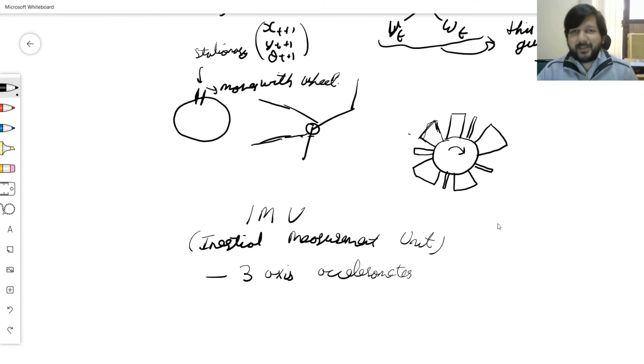Now the problem is the accelerometer is placed on this device over here. As long as I'm only moving orthogonally, I can double integrate the acceleration and get my position, but sometimes I also turn like this. Acceleration in this axis means moving in the y-axis, and after I rotate, the same motion in the same direction, the accelerometer is right here, is moving in the x-axis. So I need to know my orientation as well.